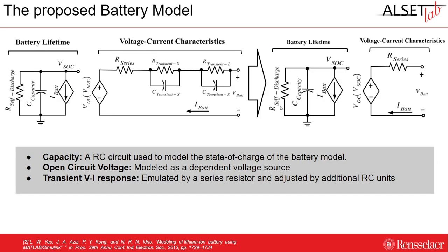In this slide, we are showing the actual battery model, the circuitry of it. On the left-hand side, the benchmark model proposed by Yao and Aziz initially is shown. The left half of the benchmark model practically represents the state of charge. It's modeled by a capacitor in parallel with a current source.